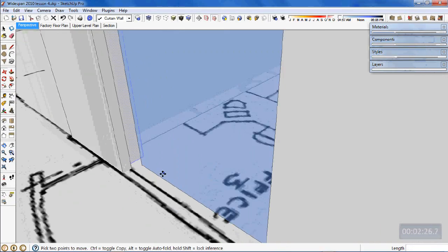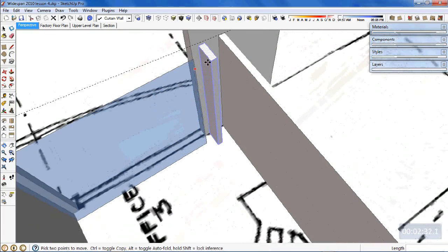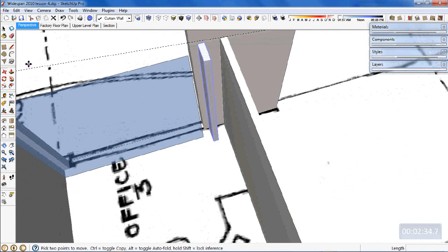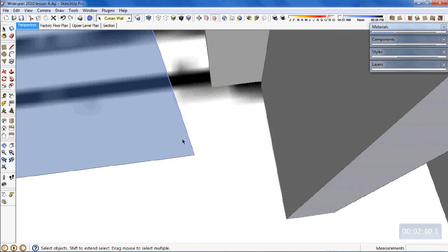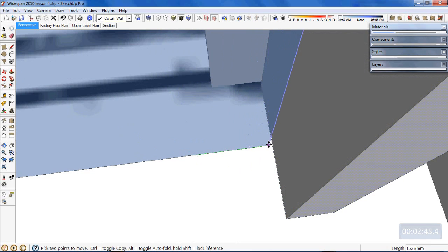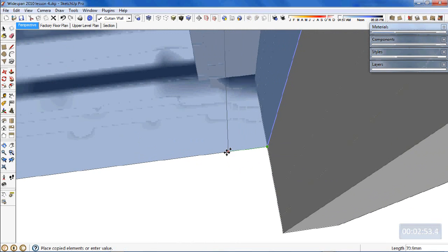There, and then that gives me another wall to pull that glass curtain wall up against. So I'll close that gap. Probably should close that gap still with a little 10mm joint there, but if I just move initially that wall in that direction until we got that end point there, I could then pull a copy of that edge back 10mm. This would be one way of doing it, and then I could delete this little part here, and that'll open up a little 10mm gap there for me.